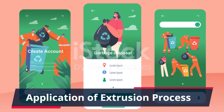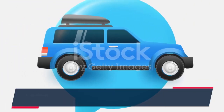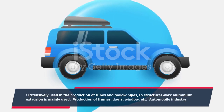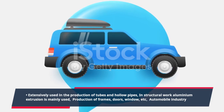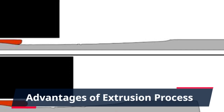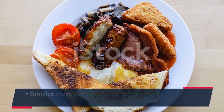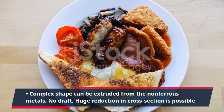Application of extrusion process: extensively used in the production of tubes and hollow pipes. In structural work, aluminum extrusion is mainly used for the production of frames, doors, windows, etc. It is also used in the automobile industry. Advantages of extrusion process: complex shapes can be extruded from non-ferrous metals, no draft, huge reduction in cross-section is possible.